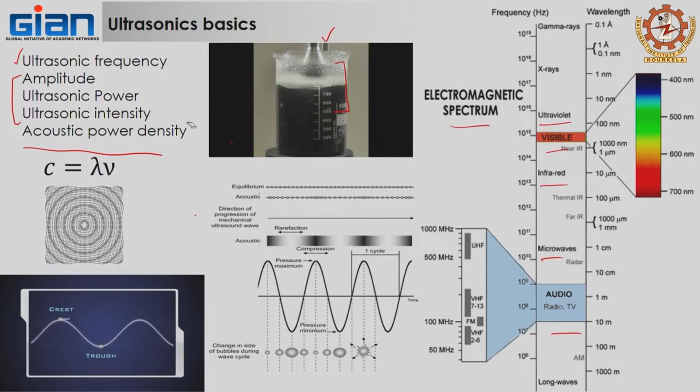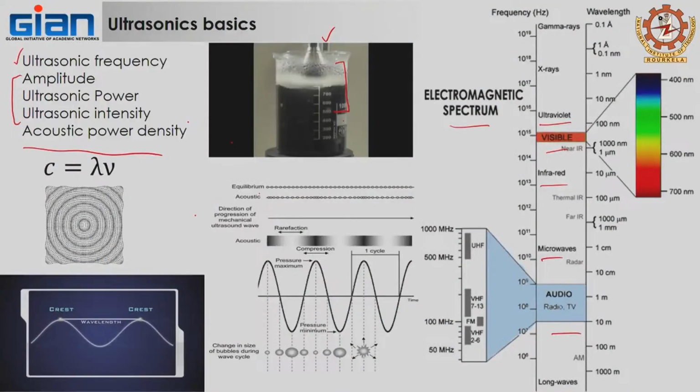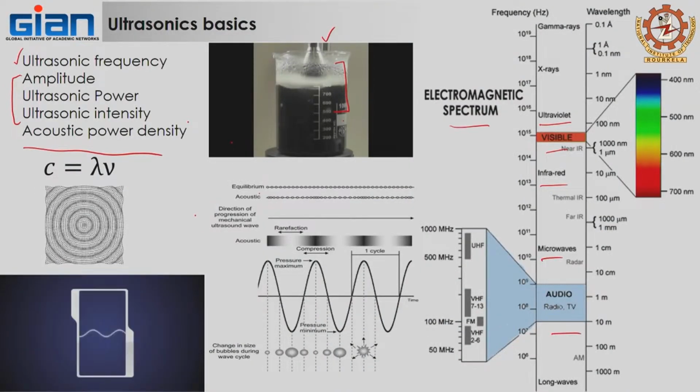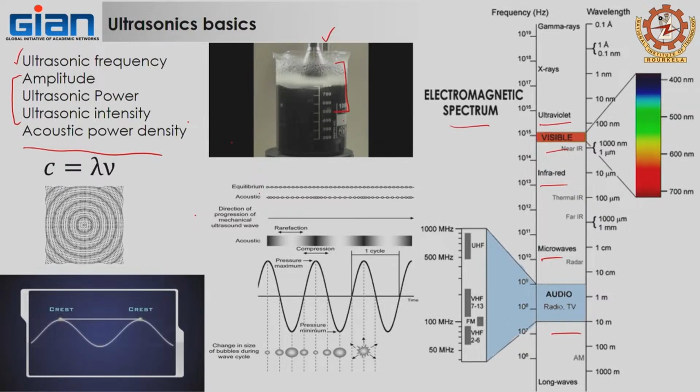Now another thing related to this ultrasonic system is, if you did your experiment for 100 ml water and now you want to use the same condition for 200 ml, it won't work, because the acoustic energy density distribution has changed. That is one of the limiting factors when it comes to scale up. So when you have to scale up, you have to accordingly balance out the acoustic energy or power density going in.